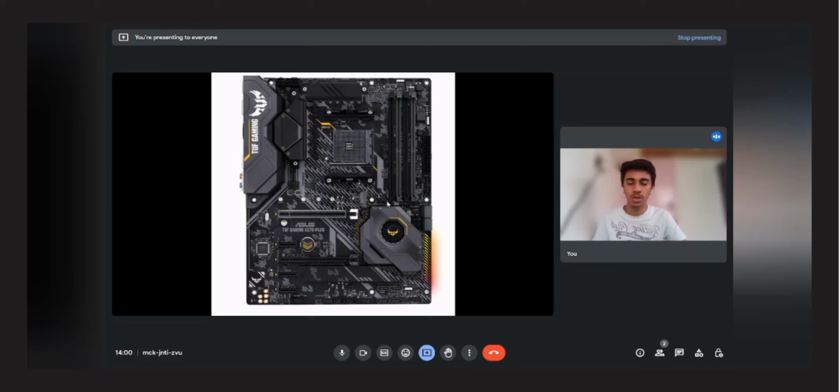I am going to explain some components of motherboard. The first one is basic input output system. This is a basic input output system which is embedded on a motherboard. It consists of instruction about what to do when computer turns on. It is also responsible for initializing the computer hardware and loading computer operating system. It also allows to interact and respond with output and input devices such as a keyboard, mouse, printer, etc.